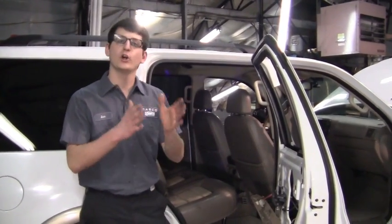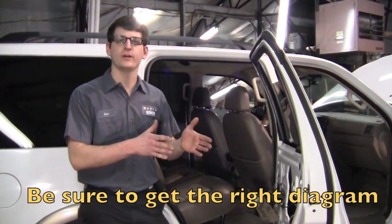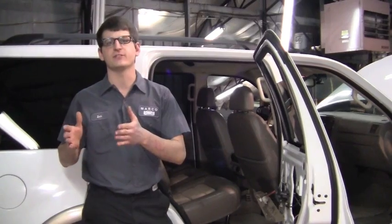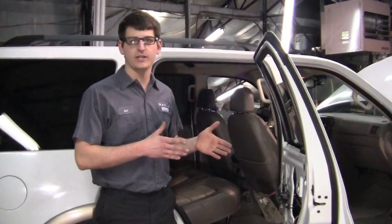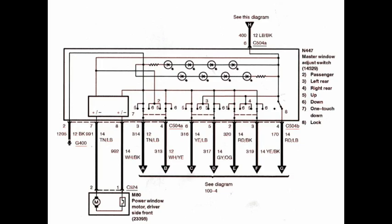Before we go any further, I want to mention that on the 2002 Ford Explorer, there was an early build and a late build. The early build being before 03 of 2002, and the late build being after 03 of 2002. Now, as we look at the diagram for the early build, we can see that in the master switch, the ground is shared to all the controls. So here's the diagram for the master window switch.